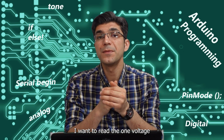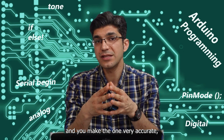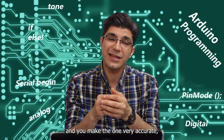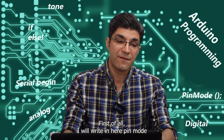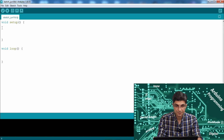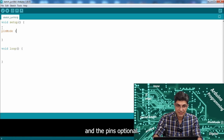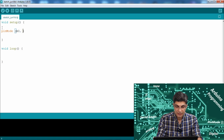I want to read a voltage and make a very accurate voltmeter. First of all, I write pinMode, and for the pin I use A0, and of course INPUT.